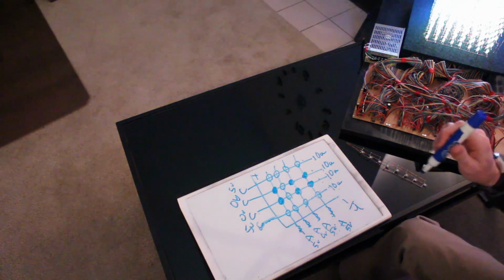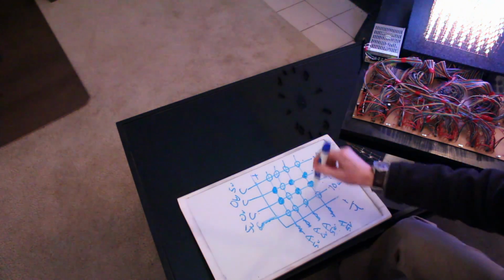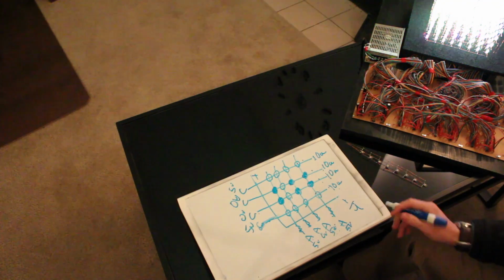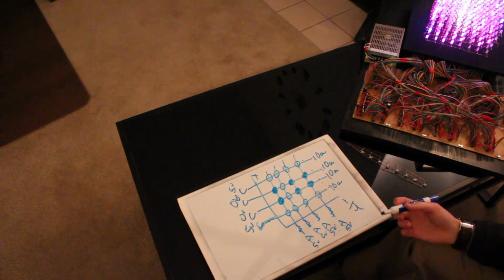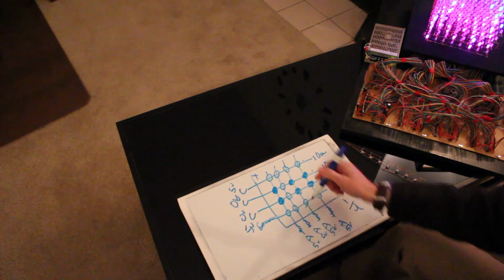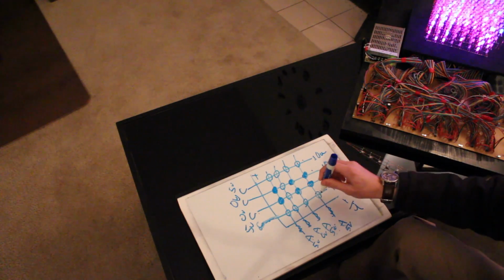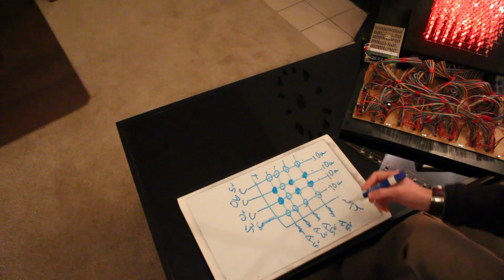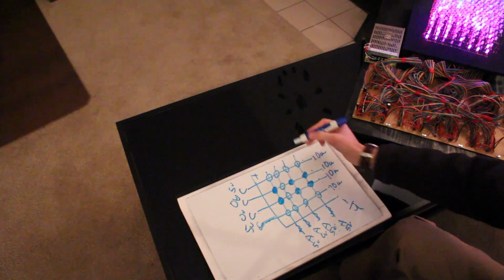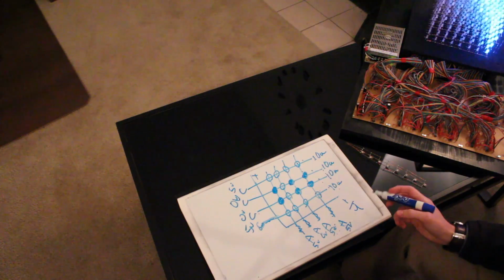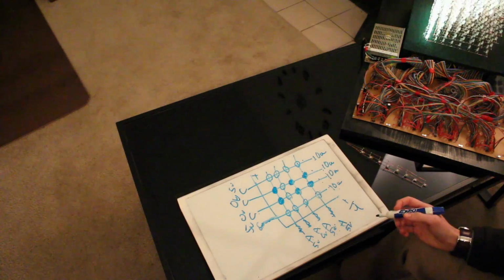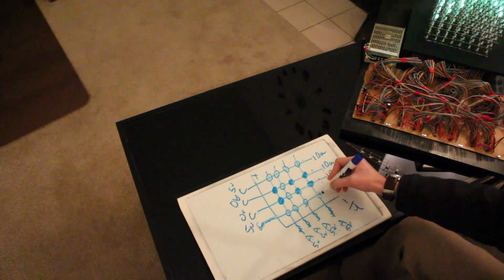But anyways, what's interesting now is you have a 1 out of 4 duty cycle for each row. So the most these LEDs can go is 25%. What if you want to control the brightness? You're actually controlling the brightness of that 25%. To control the brightness, we actually PWM this technique. So we know it goes around 1 out of 4 like this. But what we could do is PWM the pin to control the brightness, so if we want to make it a little dimmer, we don't always light it up every time it goes around.